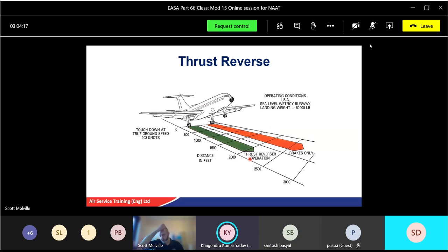Okay, if I said to you that 12% of the combustion air goes through what? What does the 12% air flow through? 12% will go directly to the combustion chamber through the fuel. Through the swirl vanes, that's the main one. Good. Now you've got inner zone and outer zone, I'll say inner layer, outer layer.